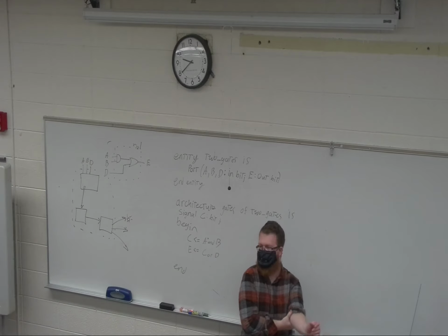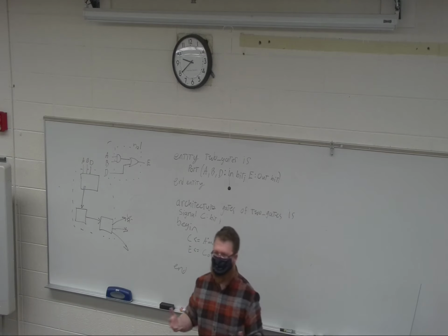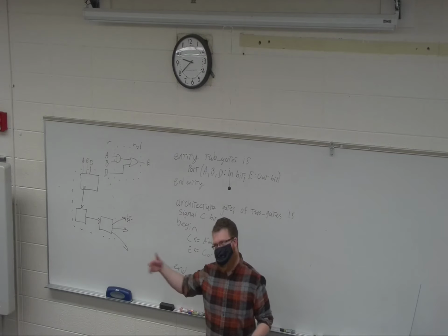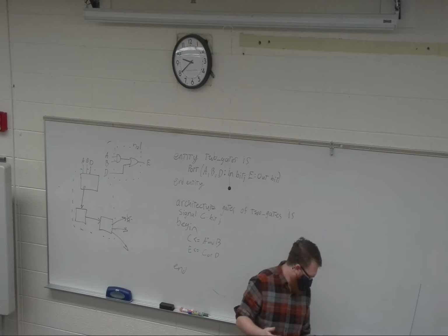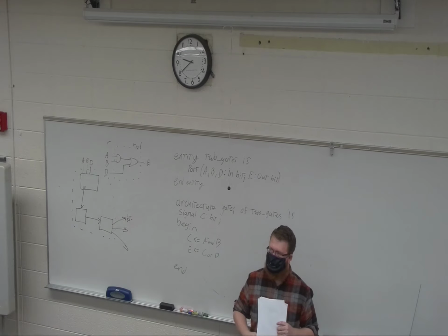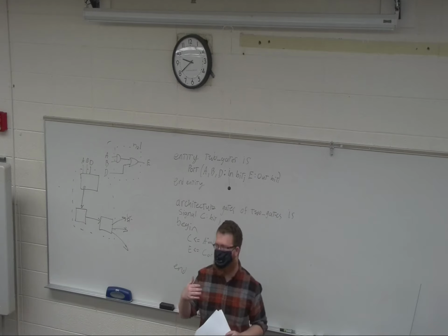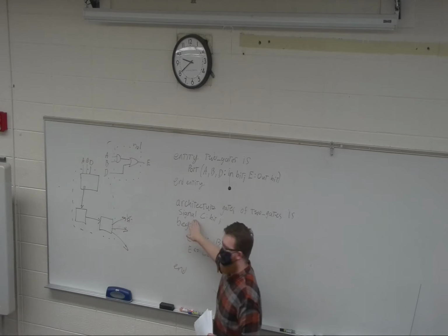Dr. Gardner, are we allowed to use in-out? You are allowed to use in-out. There is a third type that is in-out that I'm not going to address in today's lecture, but it does exist. There is actually another type called buffer. I've yet to use that one, actually. So would it be advantageous to use C as an in-out, or is that just weird? Not really, because it's not going out or in of the module, so it's best left as a signal.